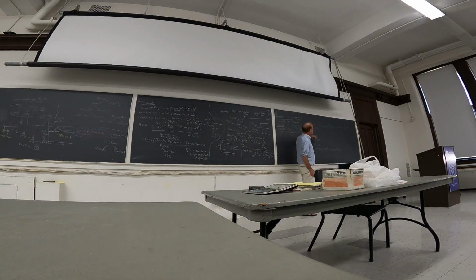So I'm comparing this point and this point, just like you do in unit ops. Now, since both are exposed to the atmosphere, P0 is the same. And if the cross-sectional area here is much, much bigger than the cross-sectional area of the pipe here, I can ignore this, because V1 is very small.